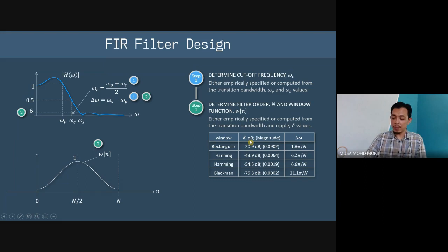If you remember, we can plot our spectrum based on real and imaginary, which doesn't give us much information, but then we plot it based on magnitude and phase. We have other types of plots too, such as a power spectrum, which is a magnitude square, and another one, which is magnitude dB. This is actually magnitude dB.